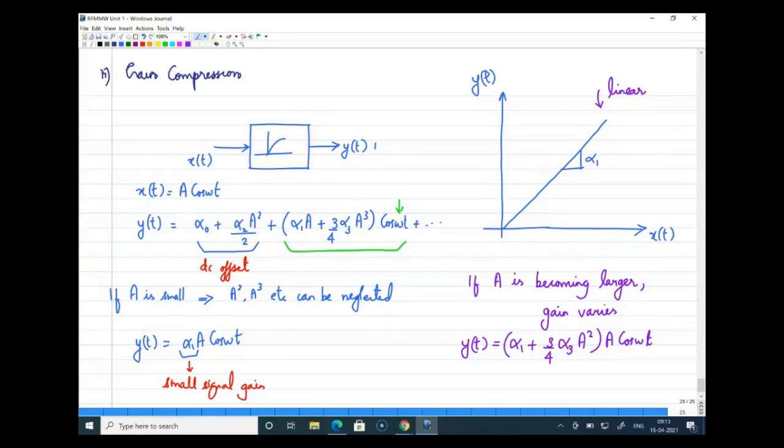Then the coefficients will be alpha 1 plus 3 by 4 alpha 3 a square, right? Now, when A is becoming larger, definitely your gain is going to vary, because this is your input signal. Your input signal is here, this is input. Now, when your A is becoming larger, this term will definitely change. This term will increase or decrease. That depends on...